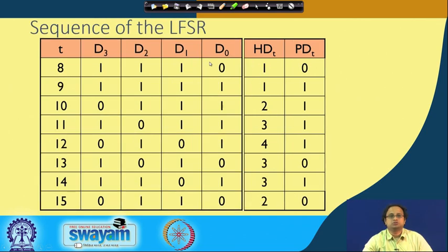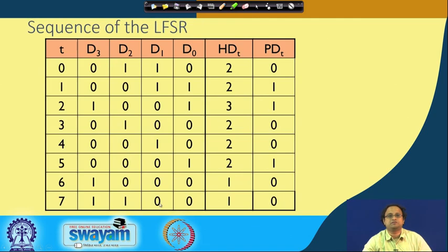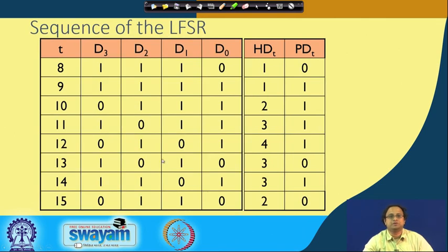Okay. So this is a continuation of this evolution. As I said, you basically go till 15, and you can see that 15 is nothing but 0, 1, 1, 1, 0, which means after this the cycle repeats. Again you can see that this 0, 4 ones exactly matches with D0. So, you can essentially prove as well. You can also go to the reference that I mentioned and see the complete proof, where we essentially argue that this PDT is indeed a delayed sequence of these LFSR states.